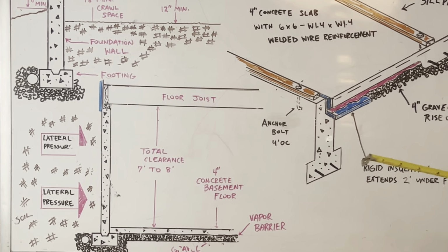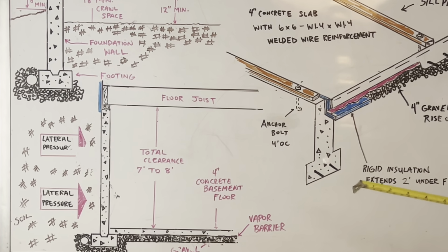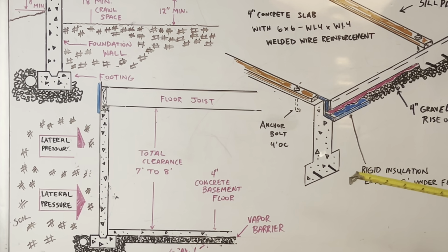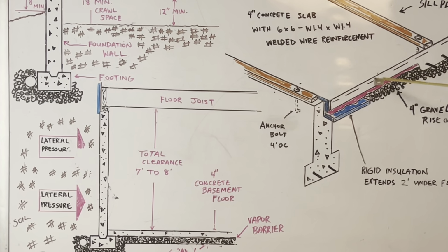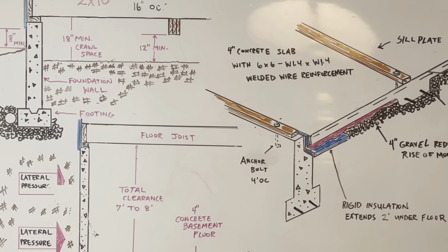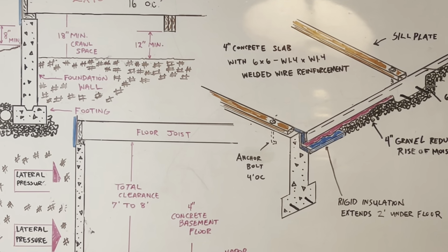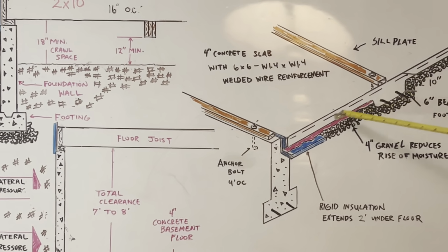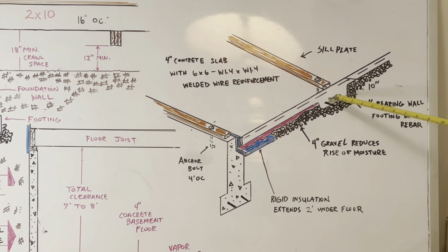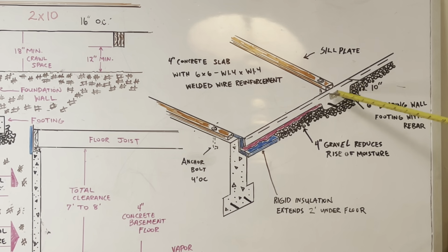Now, slab at grade, slab at grade just means the ground. In a slab at grade foundation, which this is right here, the foundation walls are combined with a concrete floor slab. This is our concrete floor slab, which is usually 4 inches, except right here. See how it's thicker right here? This whole thickness equals 10 inches.